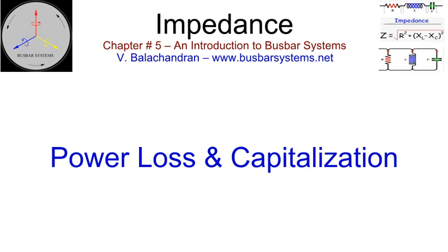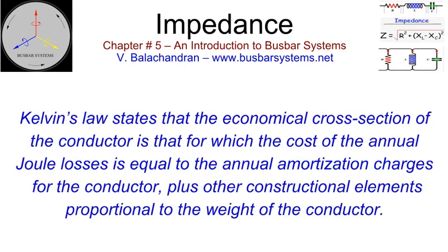In busbar systems, heat is generated by resistive losses in the conductor, resistive losses in the enclosure and support structure due to eddy currents, resistive losses in the enclosure due to circulating currents as in the case of continuously bonded isolated phase bus, and hysteresis losses in steel enclosure and support structure due to the stray field. Energy for the heat generated will be fed from the system and a running cost can be assigned to it. This can be capitalized based on the expected life.